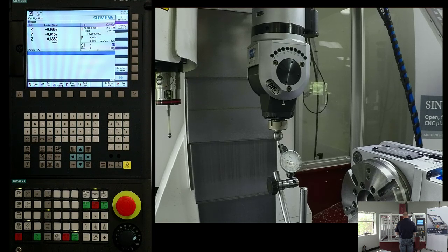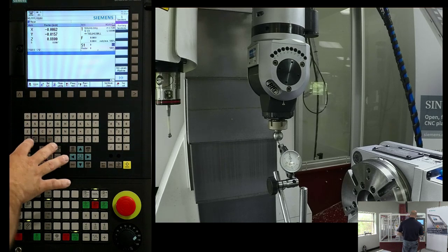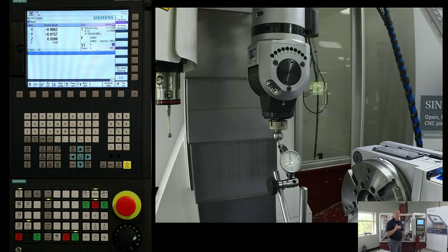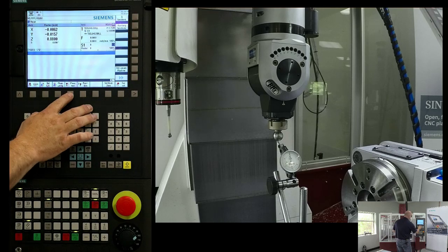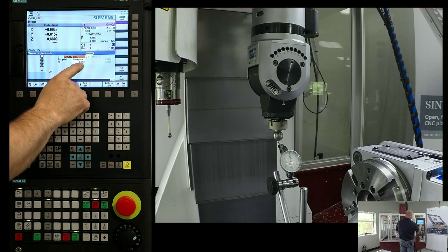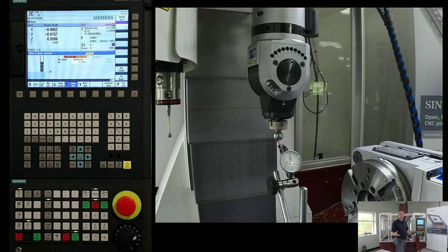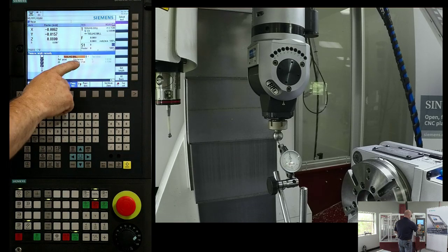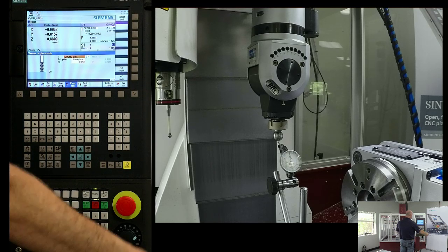I'm now going to move the machine to a 0 point, right? And now we're going to set a tool length offset. Now typically I would just set a tool length offset right here, but when you're doing a tooling ball check, I actually want to work from the center of the sphere. I want to work from the middle of it. So instead of measuring my tool and measuring my length and telling it I'm at 0 now, I'm going to tell it I'm at half of my ball diameter. So I have 375 entered in this page because it's a 750 ball diameter.